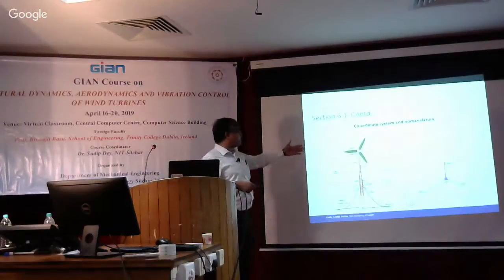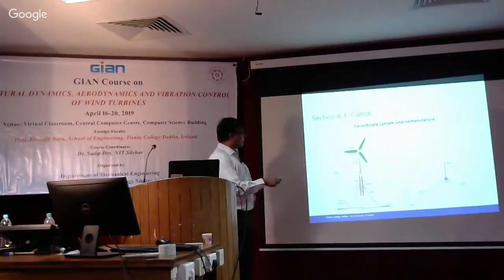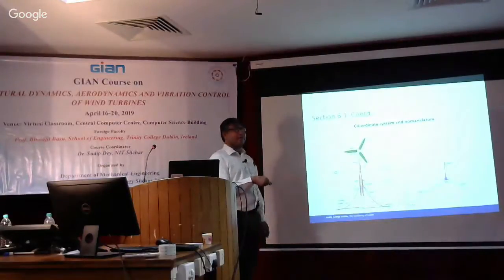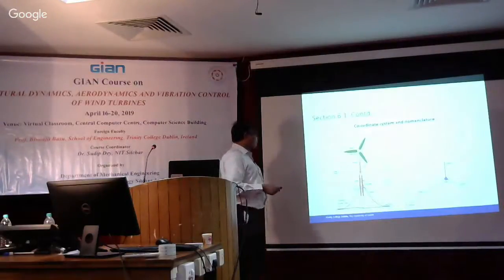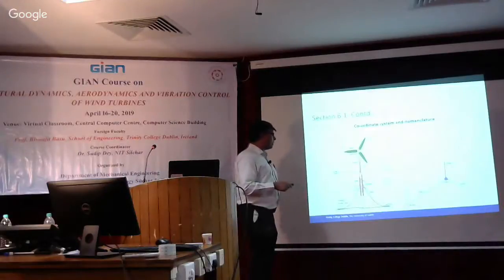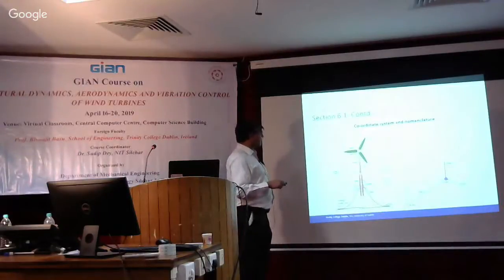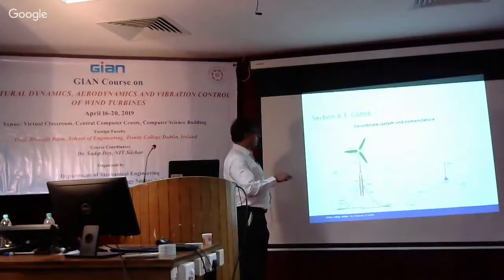But if you consider this in 2D, then you can move in this direction, and so you have the heave and you have the sway in this direction, or actually it depends on how you call sway and surge, one of the two. And then in terms of the rotational degrees of freedom, the only one you can have is basically the pitching motion, right? You don't have the yaw or the roll.